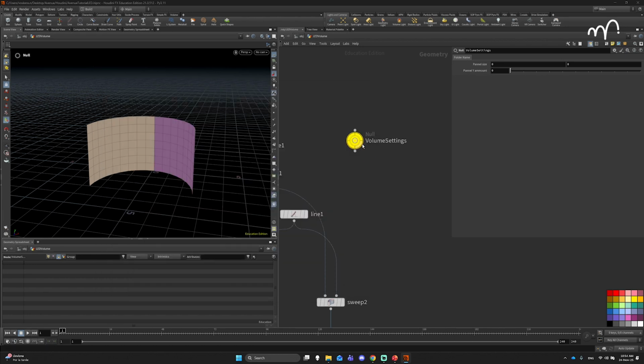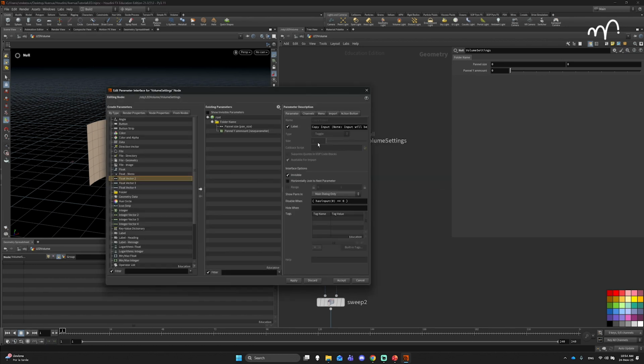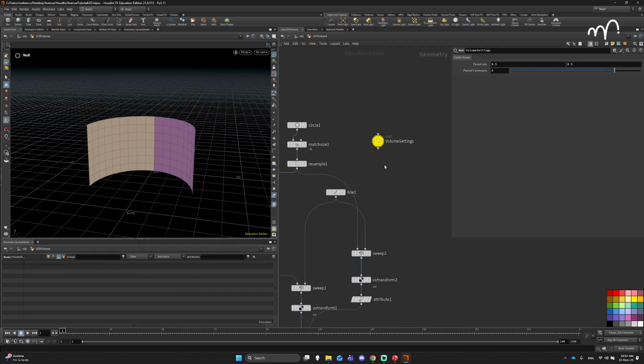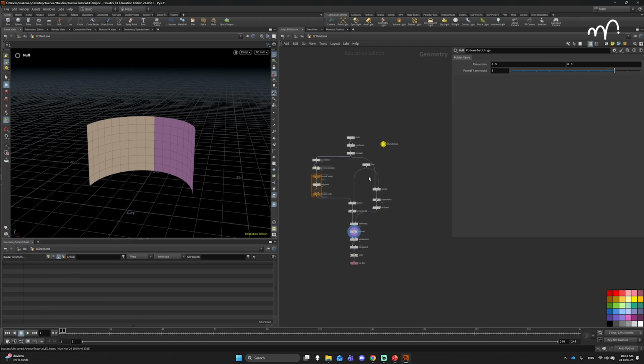They're now set to 0. Maybe we want to add some defaults to that. So we can go here into the channel itself and set this to 0.5 and 0.5 for the default value, and the amount of panels we're just going to make it, I don't know, 7, 8, something that would make sense. Obviously if you have a real XR stage, you put in your values so you can tweak it from here. But now we want to hook these parameters up to the actual nodes that drive the system.